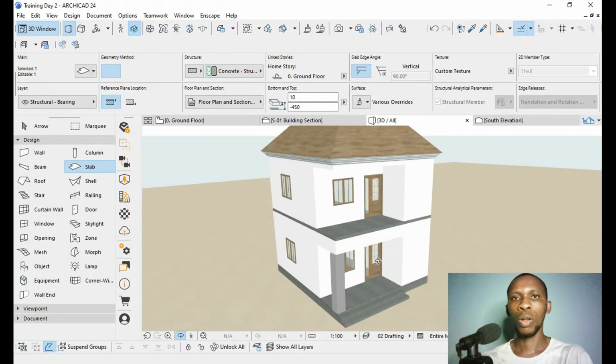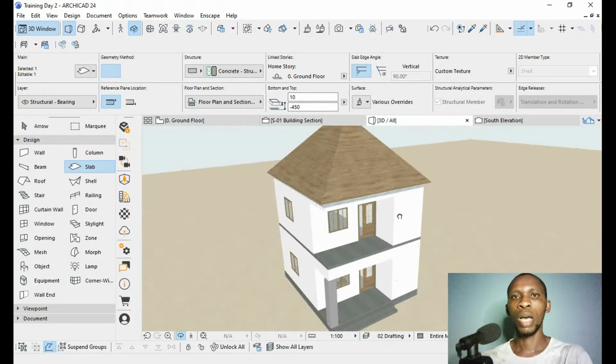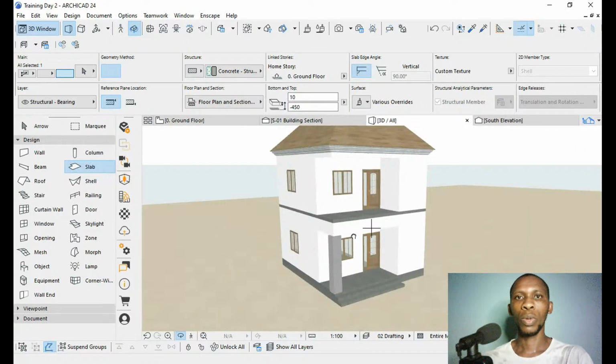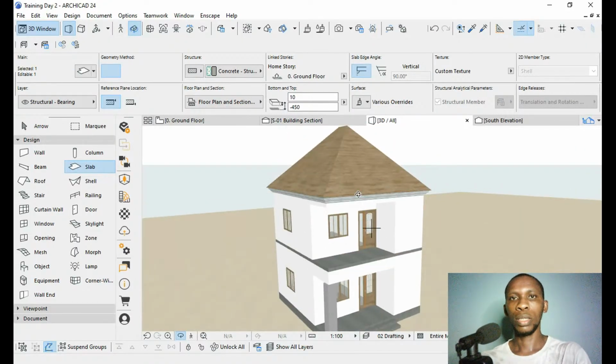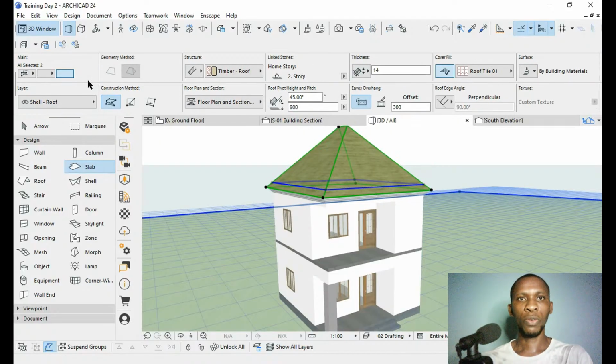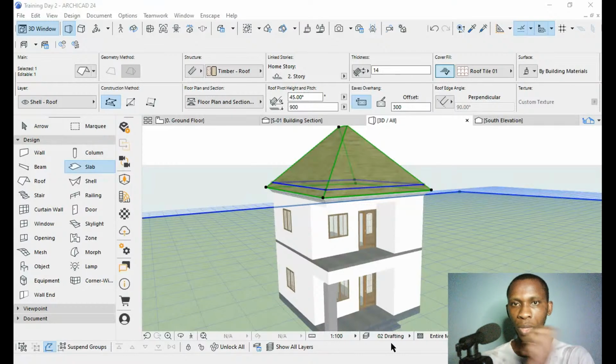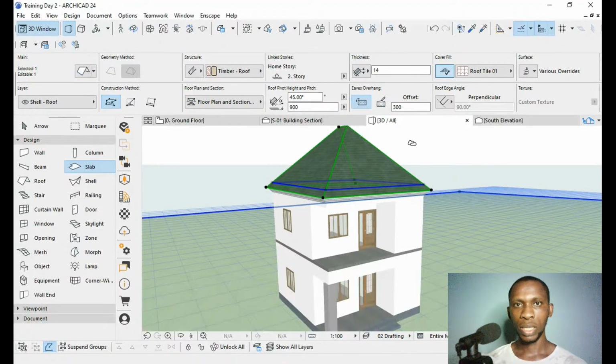So we can actually change the color or the type of roofing material we are having. Let's go down and select the roof, and then go to the roof settings, then to model, the surface of the model, the roof, the top surface. We have the roof areas. These are roof materials: asphalt shingles gray, roof tiles French brown. Let's make use of asphalt shingle gray. This is roof tiles. Okay, let's make use of this one. Then click on OK. So we have this set up here.